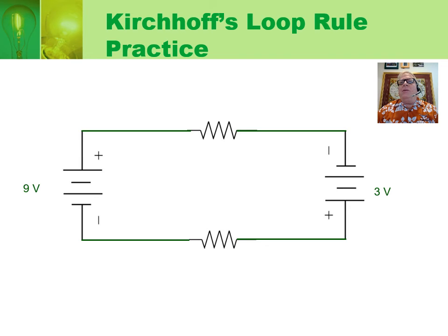And then we would go through the potential difference again. So if you start with plus 9 volts, minus V, let's call it, minus 3 volts, minus V gets back to 0, that tells me that each of the resistors must take away 3 volts in order to get back to 0 when you get back to the starting point.